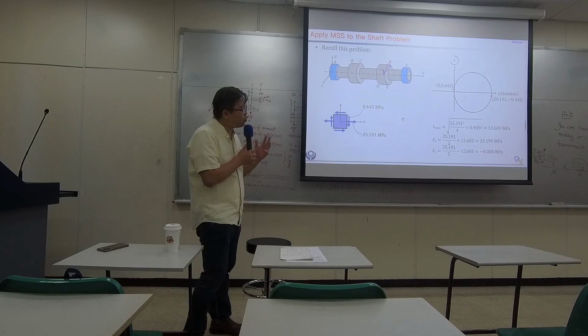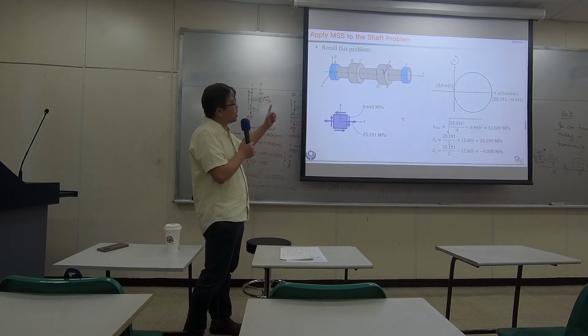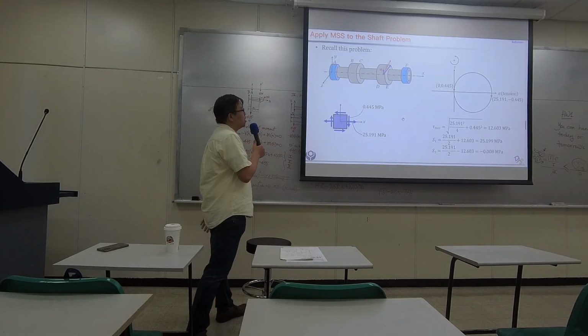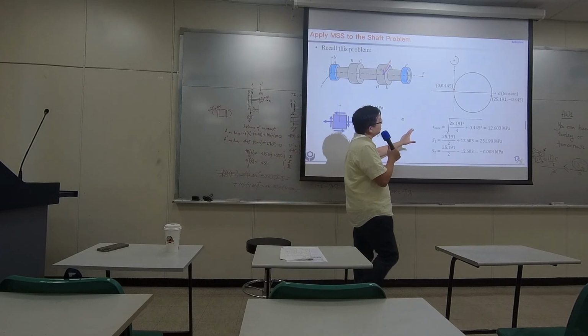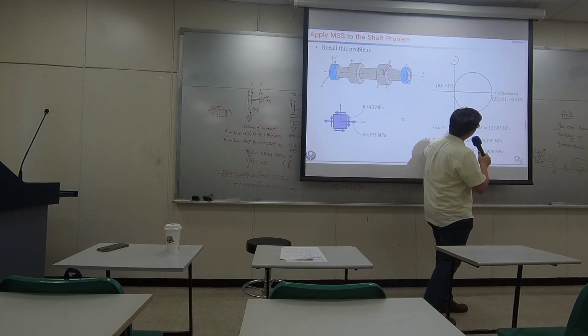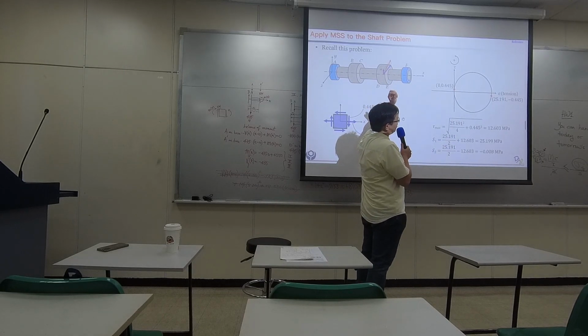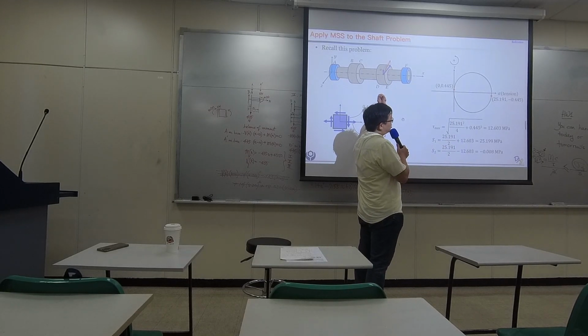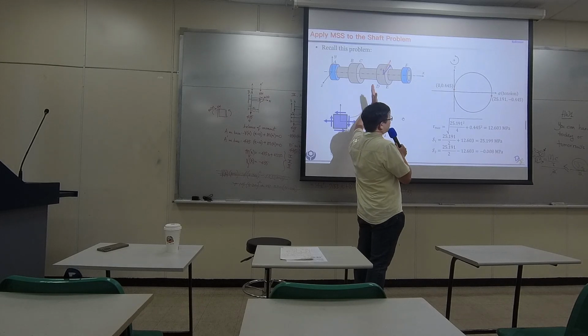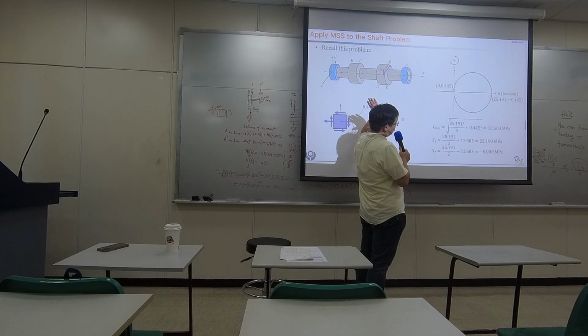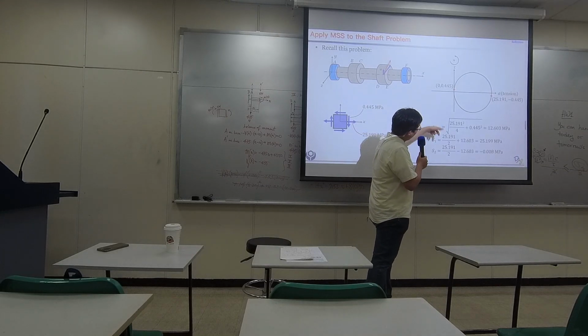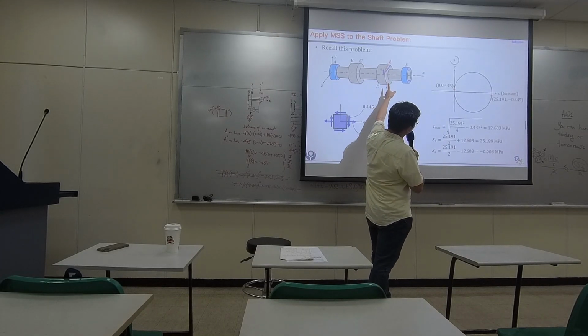But if we want to study this in the exact same problem, earlier we talked about how the Mohr circle could look like in this particular problem. This is the position where we have the maximum stresses, maximum moment, so it should carry the maximum stress. So we draw a Mohr circle at that particular position.